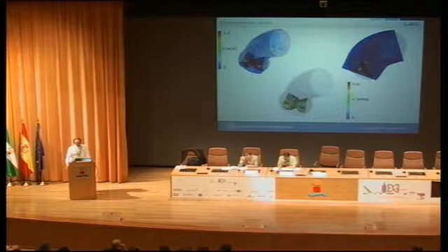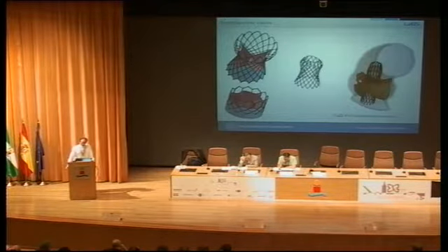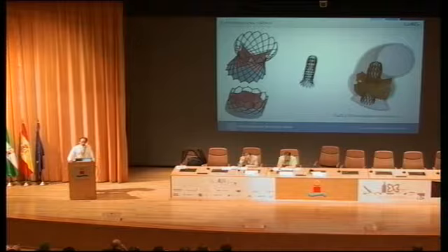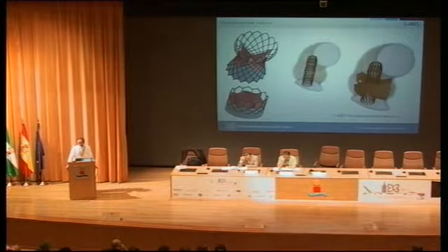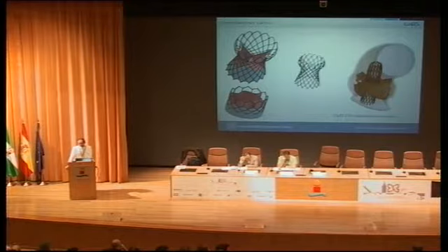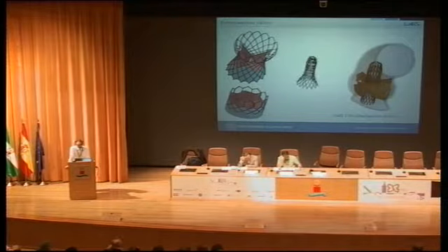When you have a model like this, you can think to make a model of the valve, try to crimp the valve, and position the valve inside the patient-specific model and make a more realistic simulation which takes into account, for example, in this case also the presence of the calcium, and then you can evaluate clinical parameters like the regurgitation, if any.